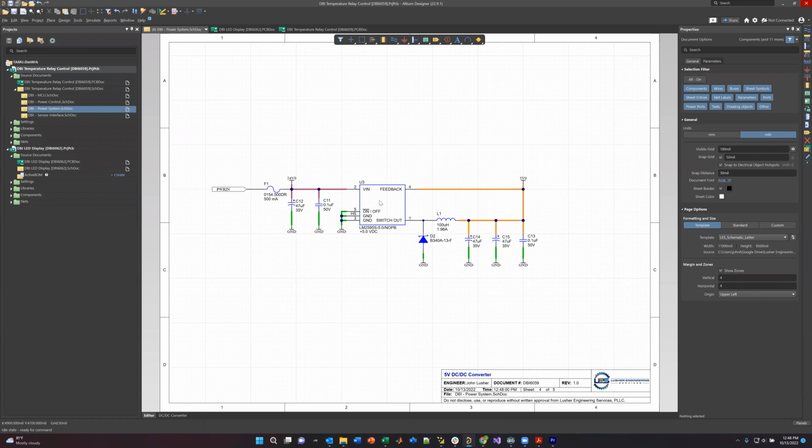Wires like that connect things, everything you're probably used to already from a schematic. There are ground ports like this. There are power ports that look like this, in this case a bar. Now, both of these are actually identical, because I can select and make this earth ground again, or I can make it a power ground, rotate it, and hit the space bar. You can probably hear it in the background. I hit the space bar, and it rotates the part.